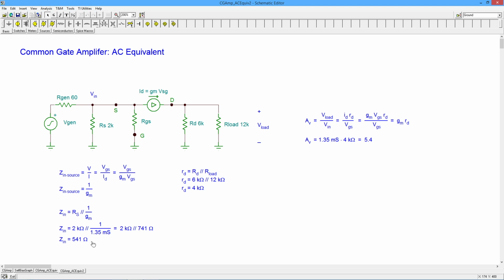Again, I'm going to draw a parallel, no pun intended, over to the common base amplifier. We don't see a particularly large input resistance for a common base amplifier. You know, the Z in emitter is pretty small. It's a function largely of whatever our r prime e is. So, you know, 1 over GM is kind of like r prime e for a bipolar, right?